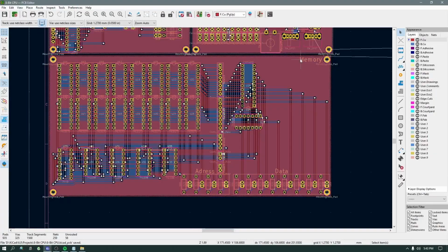The last board here is memory. It contains 64 bits of memory, or 8 bytes. The 16 chips near the top left are the memory chips, and the rest are for the control circuit. Like the registers from before, it has a read enable and a write enable, but it doesn't have an erase function. It also has an address line, which is 4 bits, and tells the memory which memory cell to use.